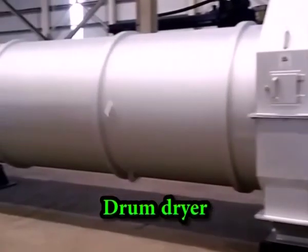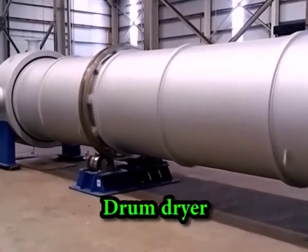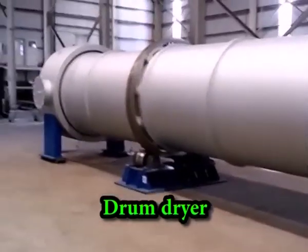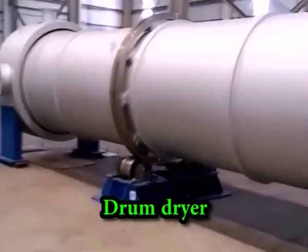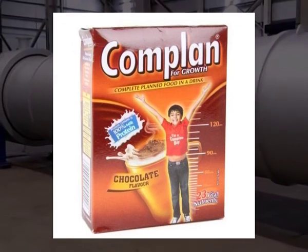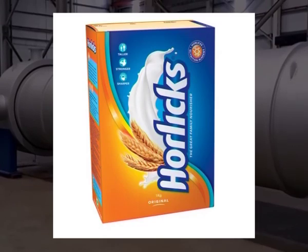In drum dryer, a layer of thin liquid is spread onto the rotating drums, which are heated by steam from inside. The dried layer is scraped off from the drums at the end of the rotation and size reduced into powder. The bulk density of this product will be high, example is Complan, compared to spray dried product, example is Horlicks.